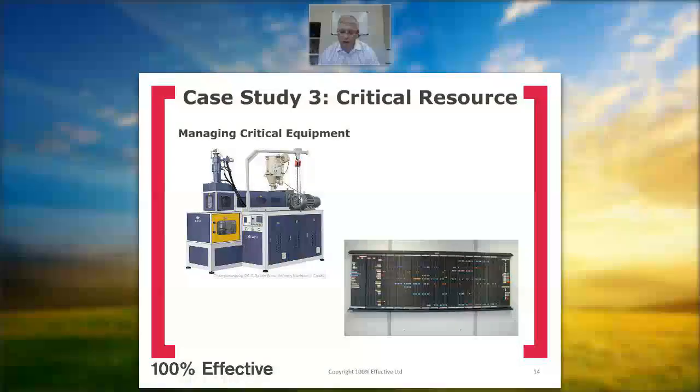So in the example shown here, when the bottleneck is a machine, there are many well-proven approaches. Here, a technical department was supplying samples of experimental resins to prospective customers, and they found that all samples had to be made on one extrusion machine, which had long changeover time between resins and was often unserviceable due to needing repair. Classic lean techniques such as setup time reduction and total productive maintenance significantly increase the output of the machine.